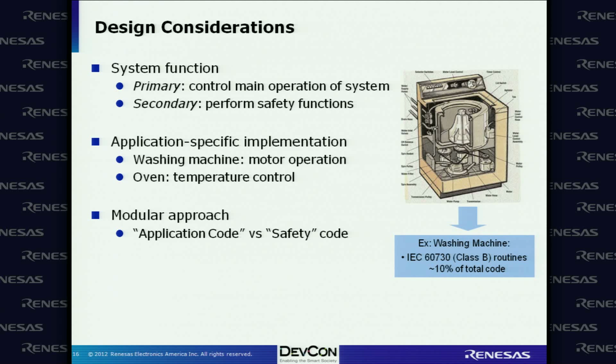Then, taking that system functionality into consideration, what a lot of designers are doing today is treating this whole safety compliance capability built into the controllers as a modular approach, right? It's done for various reasons: portability, modularity. You could reuse some of what you've done for one product in another product. So the modular approach is usually recommended. For some applications, it may not be feasible. You may have to work with the safety tightly integrated into your main controller.